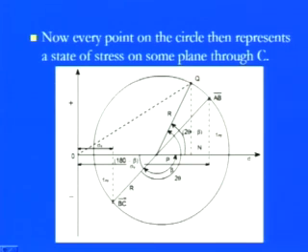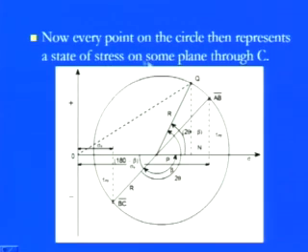So this is there. The meaning is that whatever information we are carrying in numerical form, irrespective of the sigma theta or tau theta relation, you can simply plot from the Mohr circle. So you don't have to calculate if complex stresses and complex deformation are there in the material concerned. Starting from sigma and tau, simply plot those, get the value of the radius. Once you have the radius, plot the diameter. Once you have the diameter, make the projection. Once you make the projection of the theoretical axis on the horizontal axis, you have both the components sigma x and sigma y.